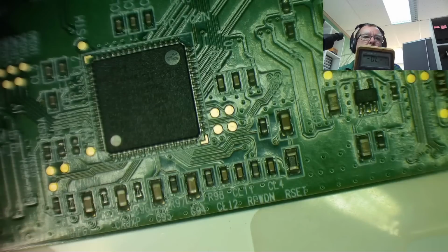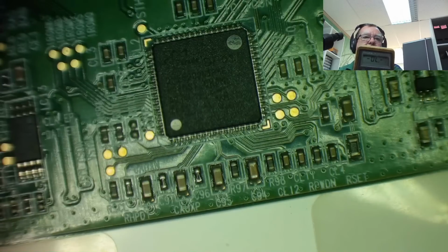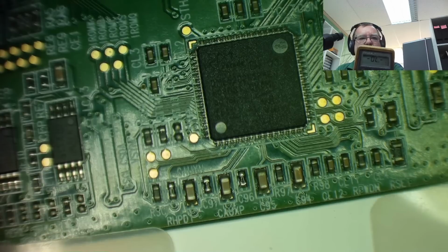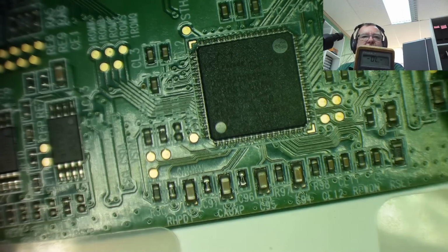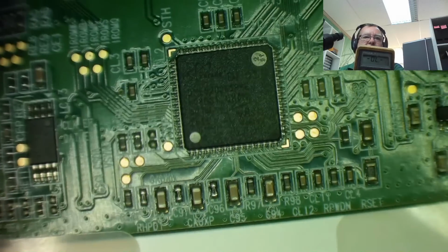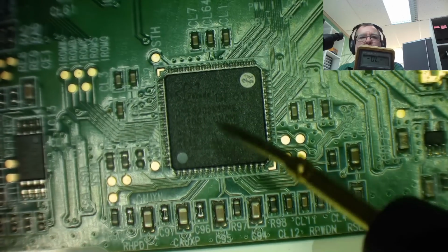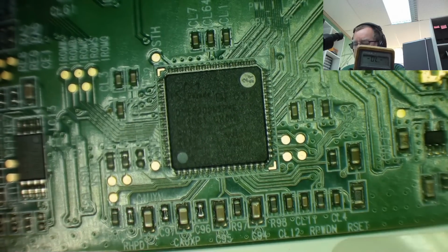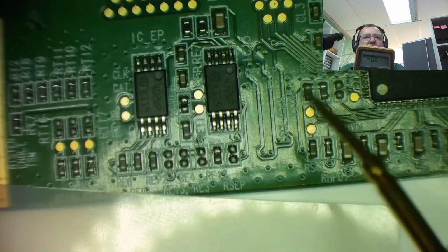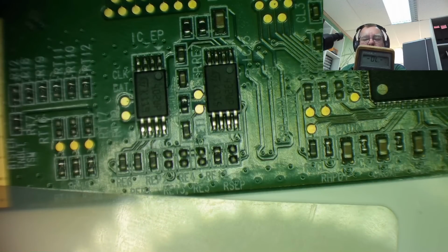So what we're going to do is connect the screen that kind of works. I can see it on the monitor. I'm going to play a video, and then come down here with the oscilloscope and see if I can see a signal coming in and a signal going out. And then I'm going to do the same on the other screen, the blank one. If one's got a signal coming in and nothing going out, I think we can pretty much say this chip's got a problem. Either that or it is a problem with one of these EPROMs. At that point I'll see what's easiest to desolder first.